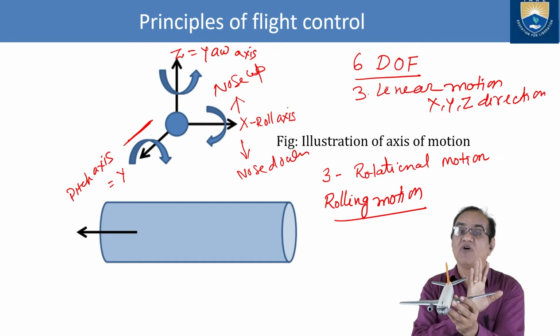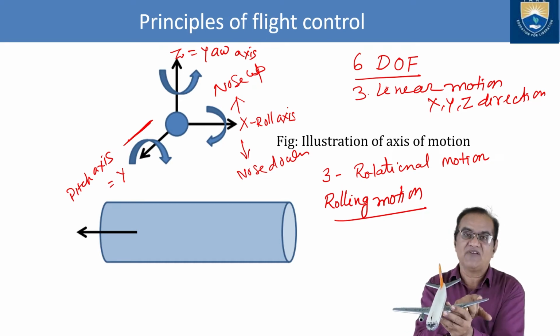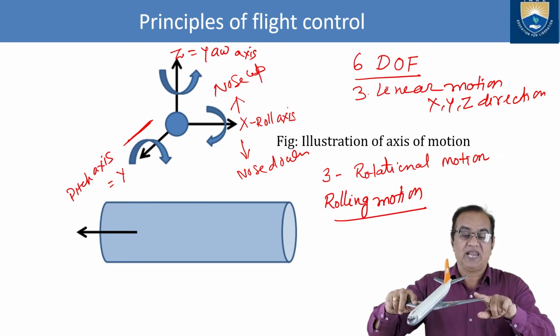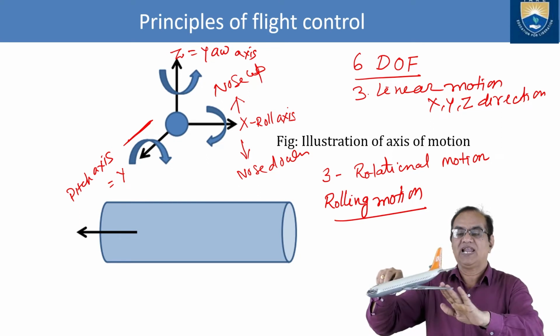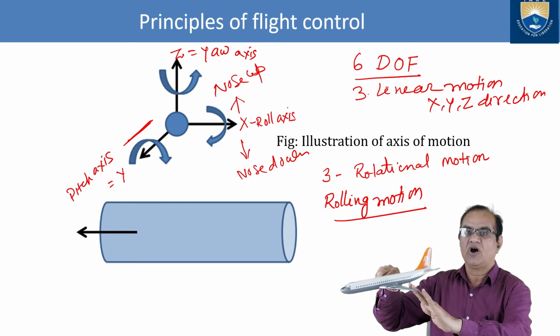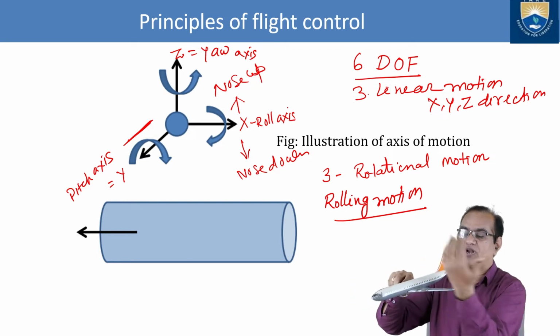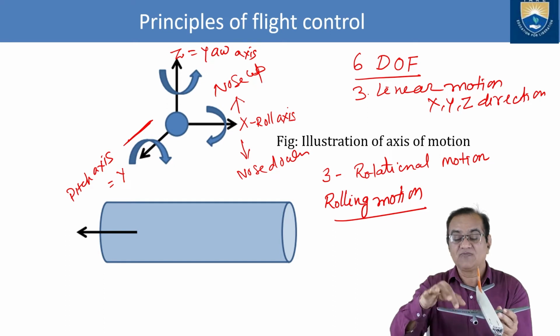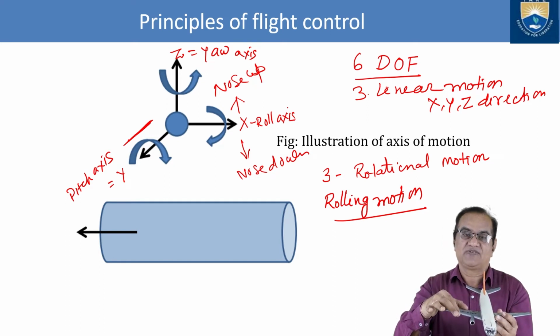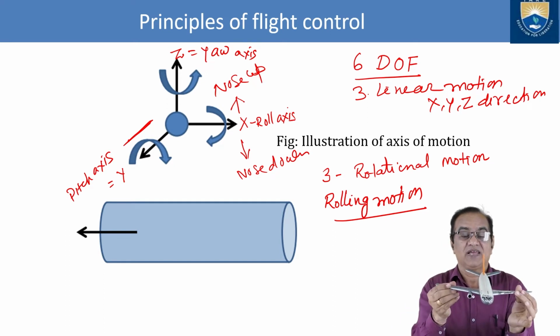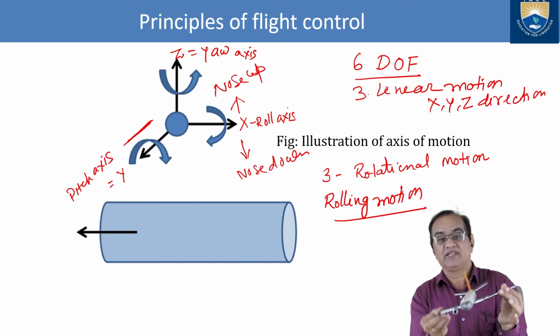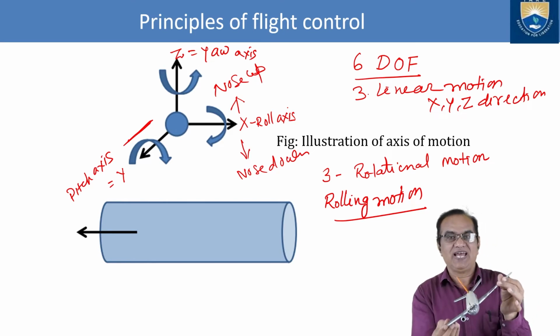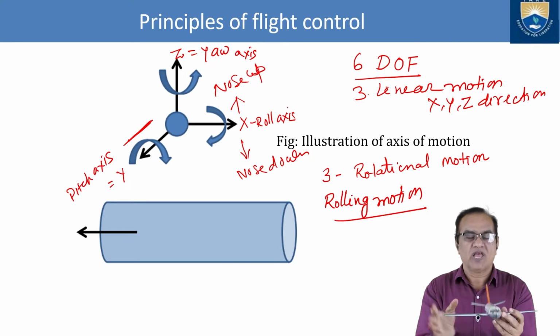So we know that if you want to make high lift, the angle of attack should be positive and it should go down. So the left aileron will go down, like this. It will generate more lift, but the right wing aileron will go up, it will reduce the lift. So the net result will be a rolling turn towards the right, and the same vice versa.